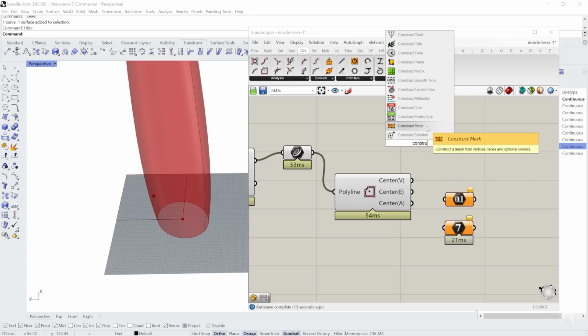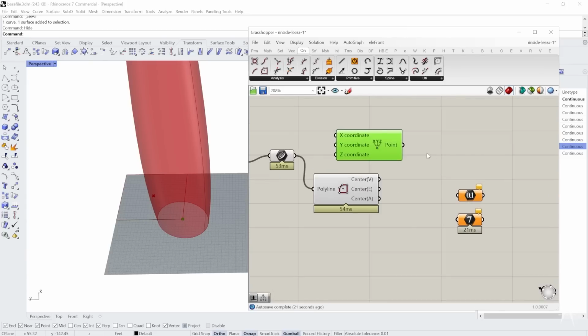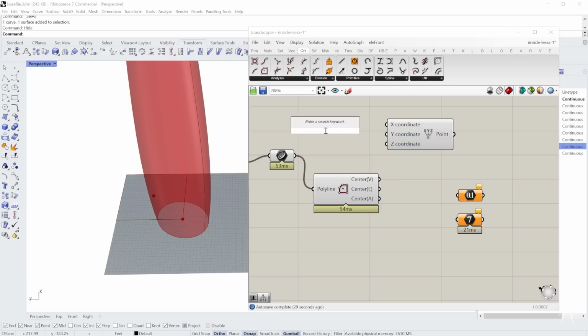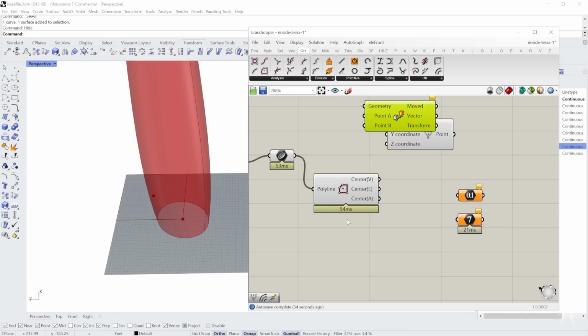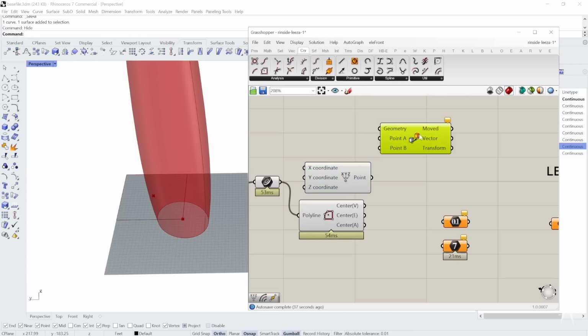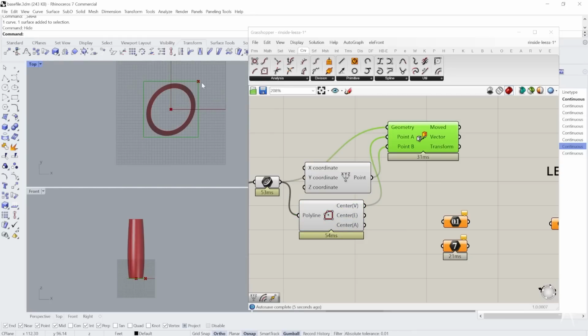We're not really going to go over too much Grasshopper scripting, because we're trying to get this into Rhino.Inside, and I'll keep expanding out to find where I need to go. So I'm moving my polygon for my surface from here over, and what we're going to do is just use move to point, with our point A and our point B, from this regular center to point B, and just moving that. Now we have something, and in our plan view, it's already over the area.